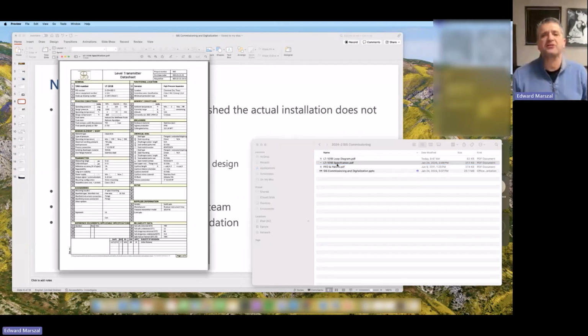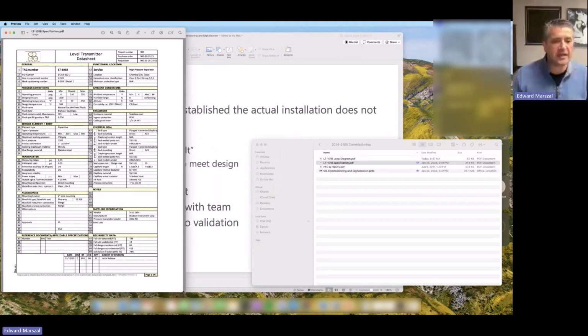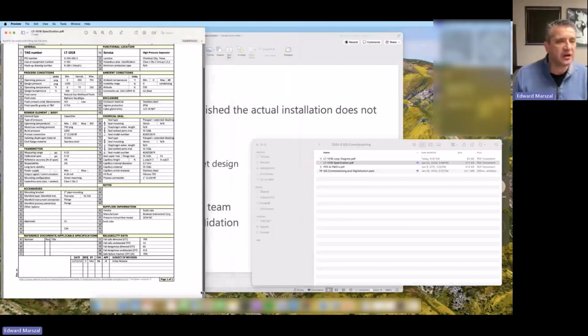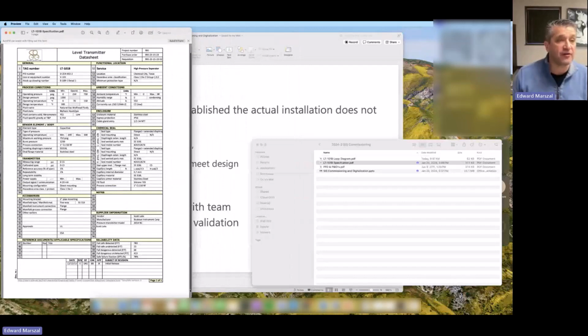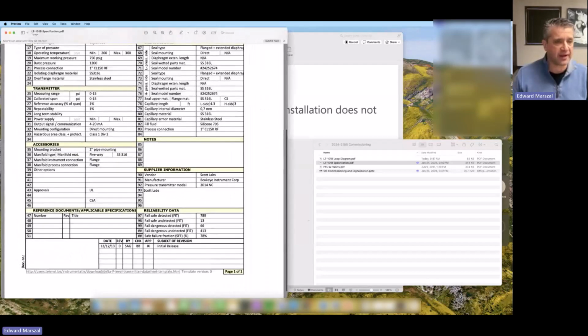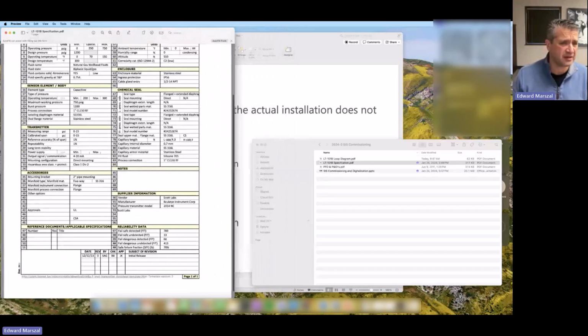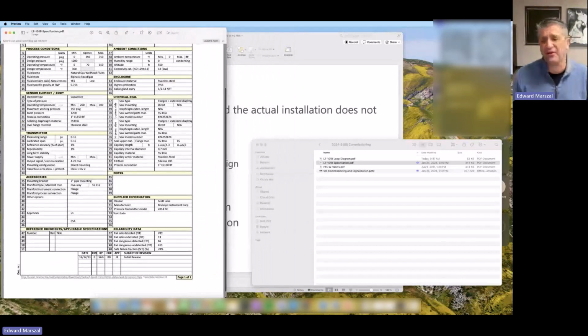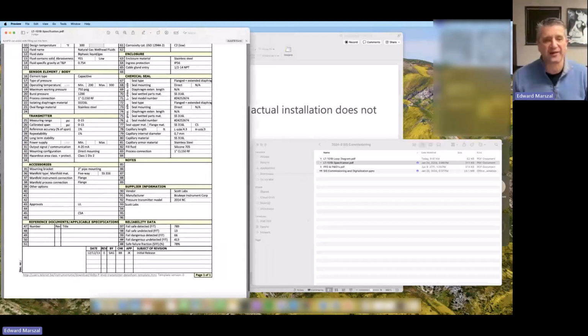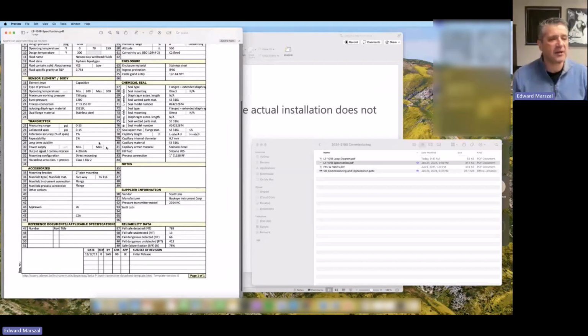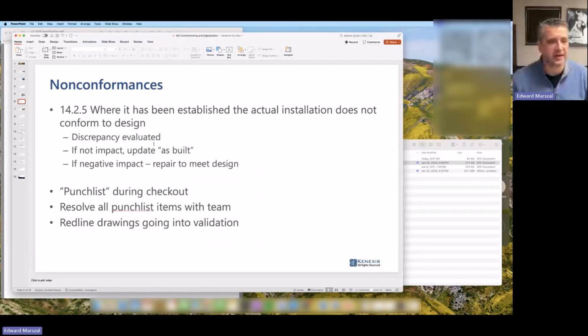So if I pull that spec sheet back up again, you'll see the range. Okay, so I'm showing a differential pressure type transmitter whose measuring range is 0 to 15 psi, which is actually kind of ridiculous. I put together this spreadsheet real quickly before the training class, but you're going to have a calibrated range that you're going to be calibrating to, and accuracy, repeatability, and so on. So make sure that when you're doing your calibration, you're matching up with what it says on your spec sheets.